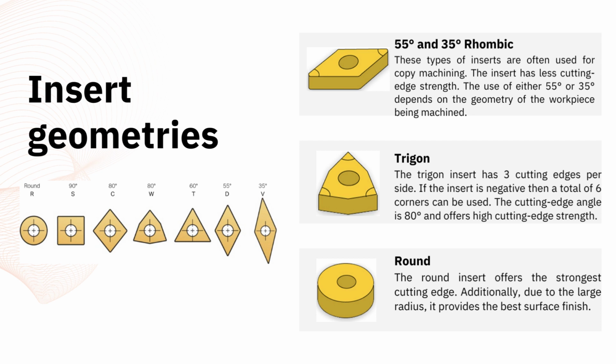However, there are a few disadvantages. The long cutting edge produces relatively wide chips and is difficult to break. Also, due to the large contact area and the long cutting edge length, the load on the insert increases.